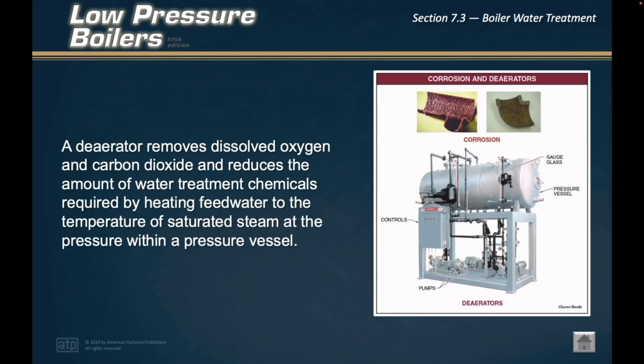Boiler feed water usually contains oxygen and carbon dioxide in dissolved gases. Dissolved gases that are not removed before entering the boiler are liberated by heat and can cause severe corrosion in the boiler, steam lines, and condensate lines. This damage can be very costly and lead to dangerous conditions.